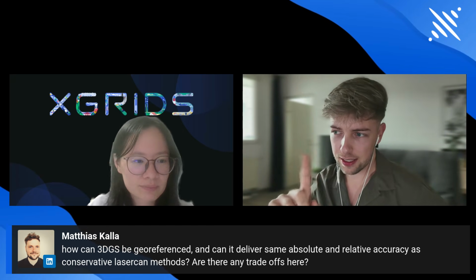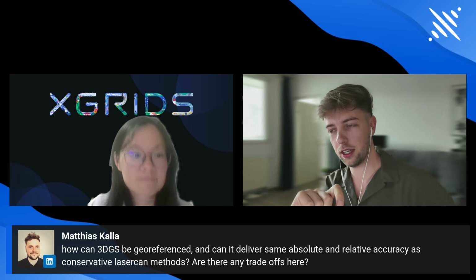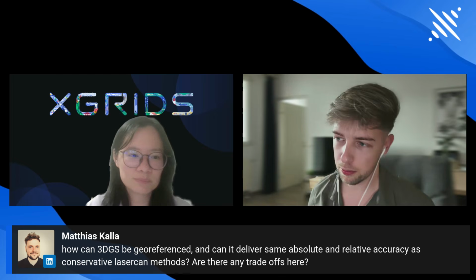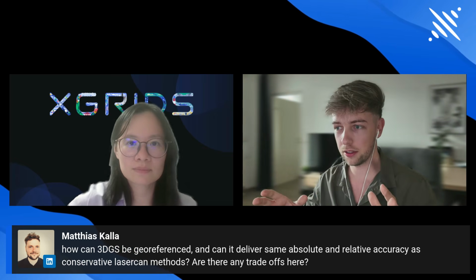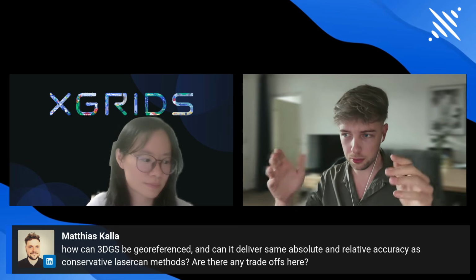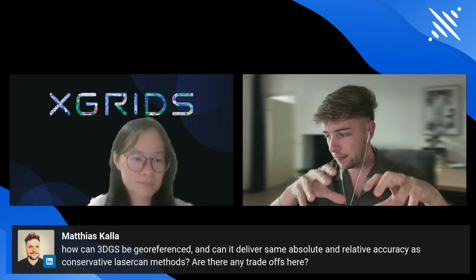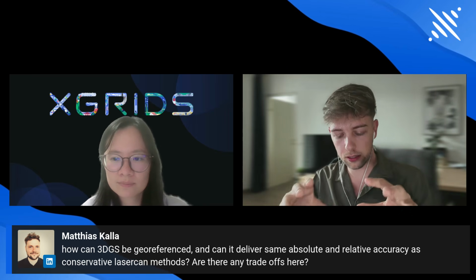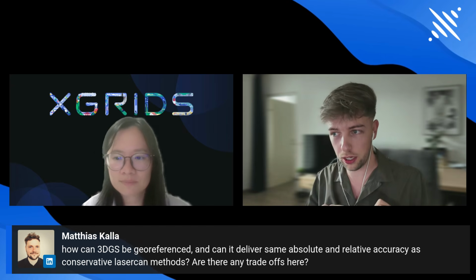Yes, it is actually an important question, because in my scanning work it is always very important that it is georeferenced. Most projects need to be placed in some kind of coordinate system, so that every plan from every planner is on the same scale and when you load the point cloud, it is in the correct position.